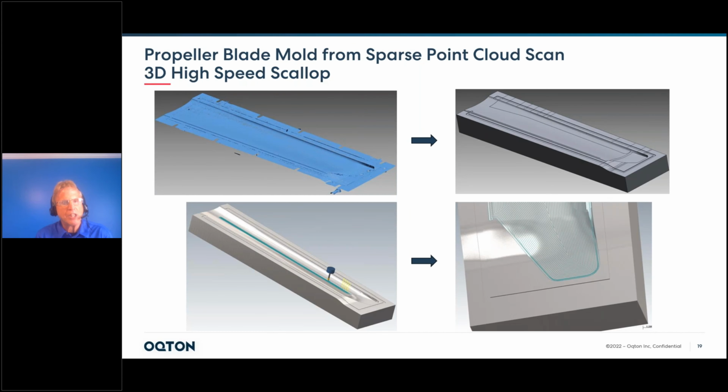We go from the mesh, we pull information from the mesh, we build design intent into the CAD, whether it's a sketch or a mesh, and then we go out and create a model and machine the model. So our final model here is essentially stepping back to how I started out this presentation. We talked about having a very sparse point cloud that we started from simply by dragging a probe back and forth on the surface. And from that sparse point cloud, we're able to produce a fully functional, fully machinable STEP model where we create our toolpath from.